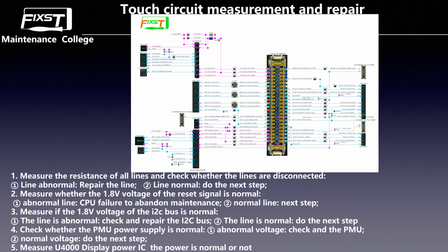If the new LCD is okay, it means that the problem is in the LCD. From the iPhone 6s onward, the touch IC is integrated in the LCD. So normally a touch problem from the iPhone 6s onward is an LCD problem.